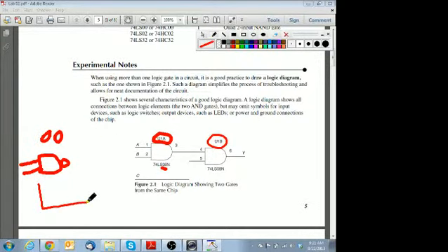So let's say that, for example, you have an integrated circuit part here. And it has some pins on it. Normally these packages will have 4 AND gates on them. It depends on the package, but they can have 4, they can have 2, whatever. But a common scenario is that they'll have 4. So each gate inside of here is going to be numbered A, B, C, or D. You have to look at the data sheet actually to find out.